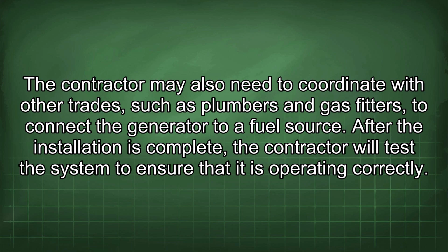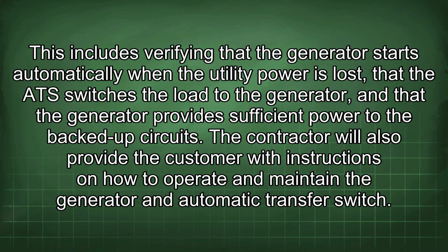After the installation is complete, the contractor will test the system to ensure that it is operating correctly. This includes verifying that the generator starts automatically when the utility power is lost, that the ATS switches the load to the generator, and that the generator provides sufficient power to the backed-up circuits.